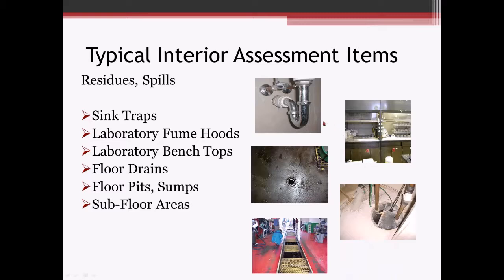Residues and spills, sink traps, especially in your laboratory type areas, you might get some accumulation of different products right there in that sink trap area. Say you had a thermometer spill, common practice in the past might have been to just take it over the sink and wash it down. Well, that mercury likes to sit right down in that sink trap. So that's sometimes a good area to check into.